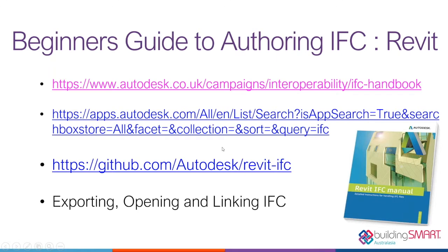I think one of the most interesting things that's happened with the Revit IFC implementation is that they've actually isolated it and separated it from the base product development. So you do get IFC out of the box when you install a new version of Revit, but now it's published as a plugin on the Autodesk App Store as an independent product. And so first and foremost, if you're authoring IFC, I'd suggest regularly checking the App Store to see if there is a new version of that plugin, so you get the latest fixes and the latest improvements in what you're authoring.